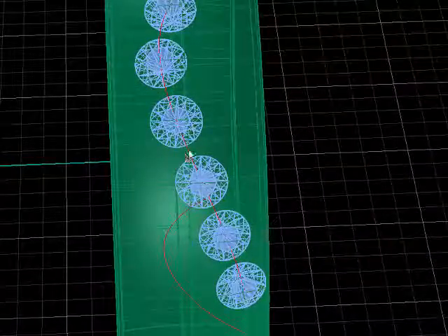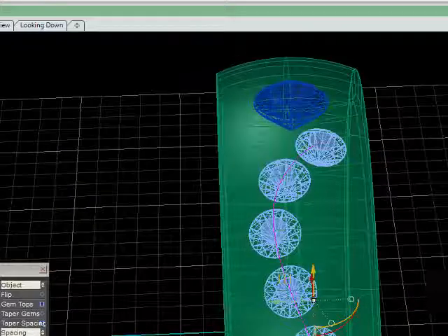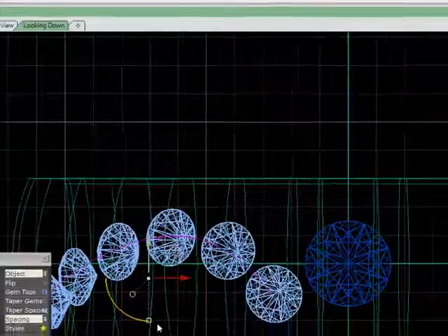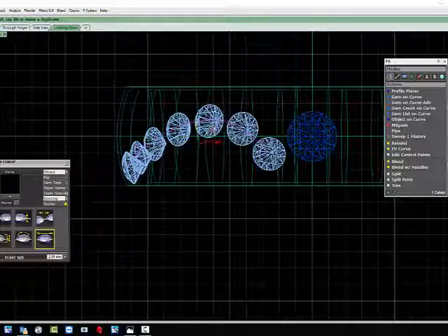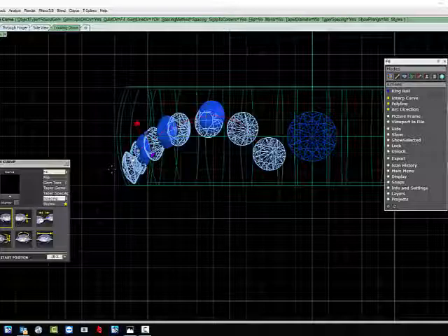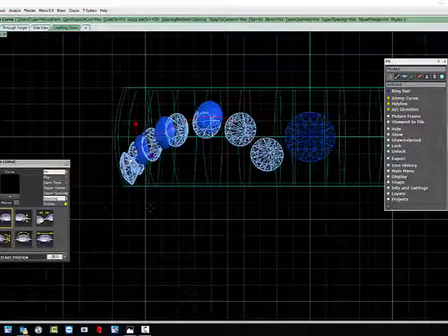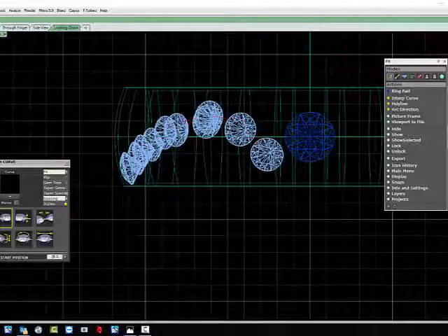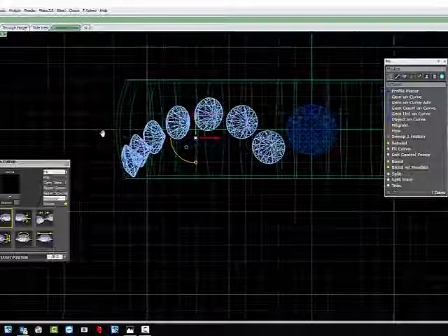If I think I need to move that at all, I can wake that up. Use the curve menu. I want to be looking down. Perhaps move the whole thing over slightly. Enter. And that buggers the whole thing up. Alright, so just be aware that if you do these things, it has a consequence to that. So press Ctrl Z or undo up here. But you've got to press enter first. So come out of that command and you're back to square one. One more time and you got to where you want to be.